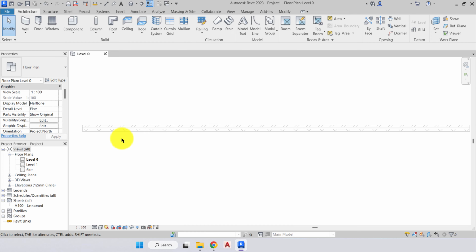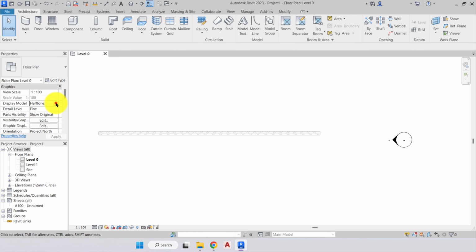The purpose of this is if we are drawing an existing house where there are no changes or refurbishments to the actual house, so we don't need to display the outline of that house in full detail. We just halve the tone, and then all of the new refurbished work will be full tone within the drawing. I'll change that back to normal.